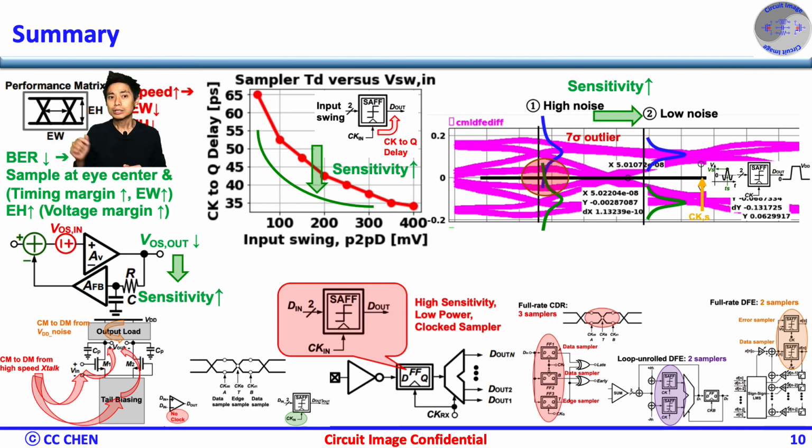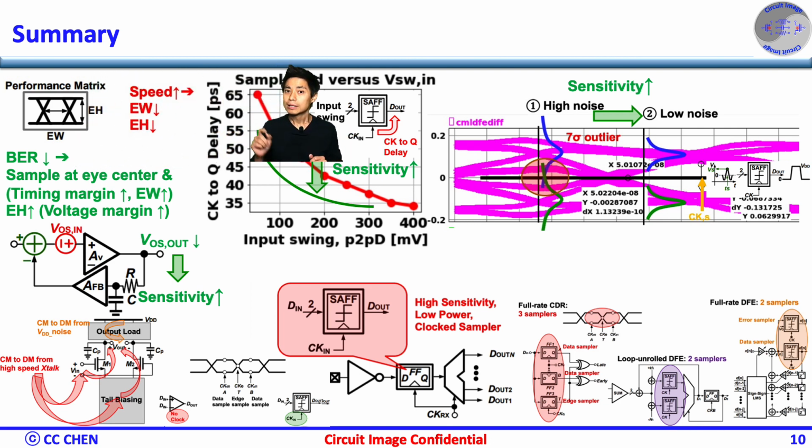Unfortunately, the channel loss scales with the speed, and the bit period, 1 UI, scales down with the speed respectively. Therefore, both the received input swing and the bit period would be too little to make the sampler generate the output rail-to-rail digital level within the bit period.